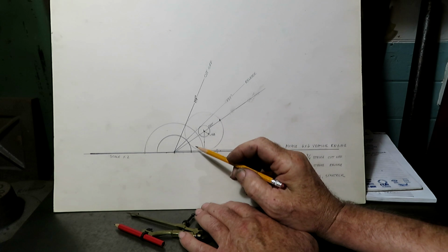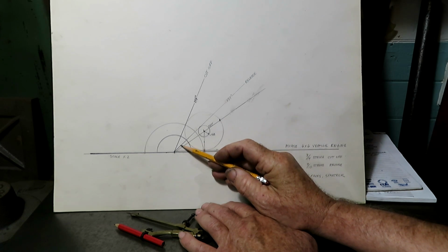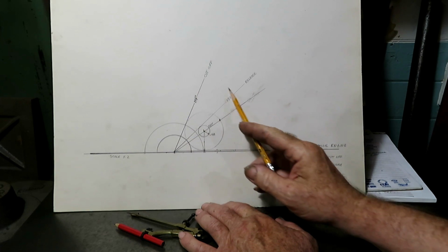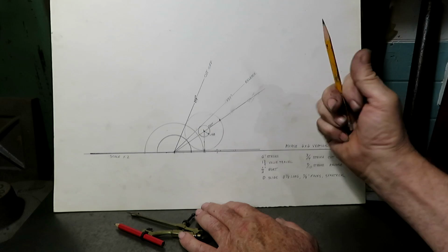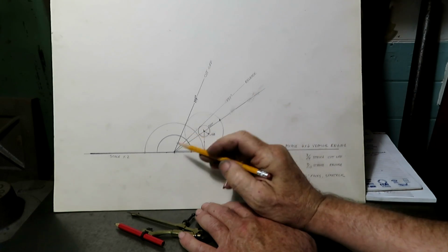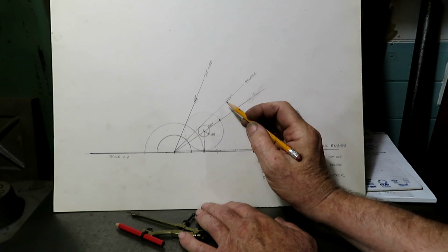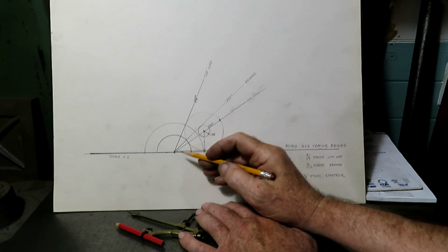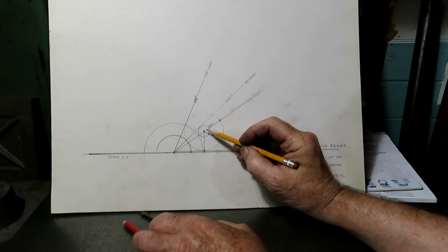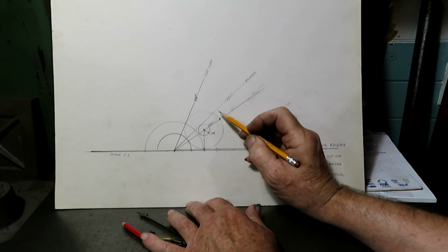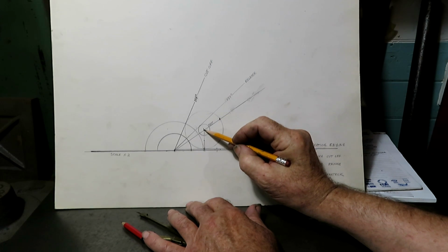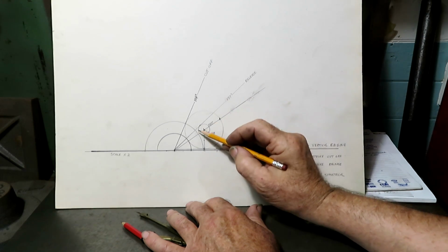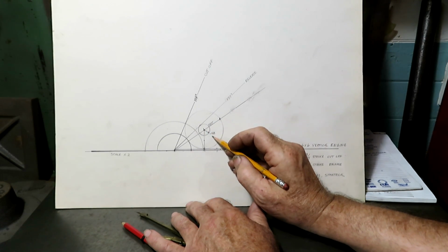And the way you find that is you draw the release line, which is at 137 degrees after top dead center, and I measured that off of the other diagram to take into consideration the rod angularity. You construct that line up through there, and then you put the compass again with a point on this same line as the intake circle, and you draw a circle tangent to that line, the release line.